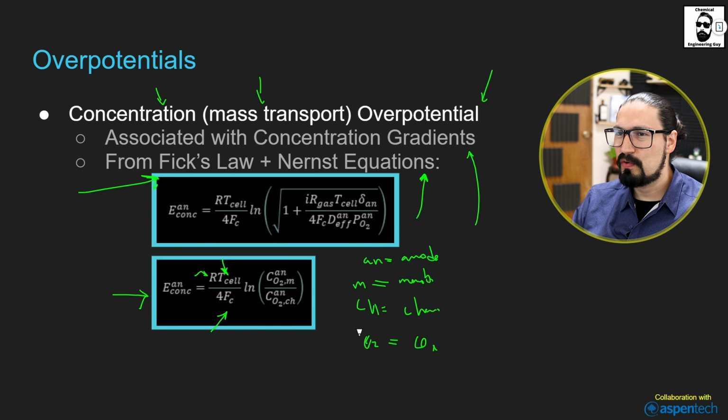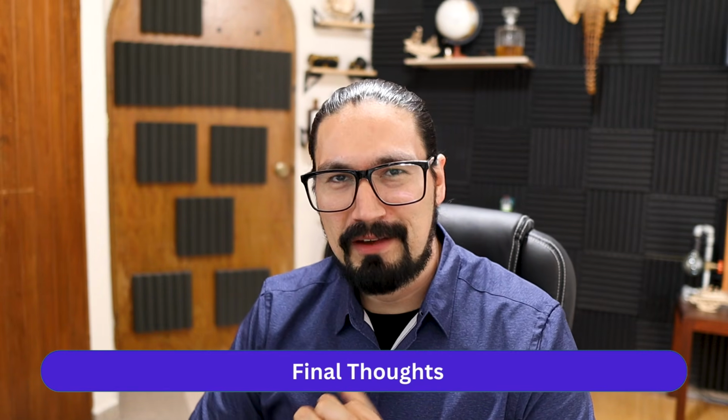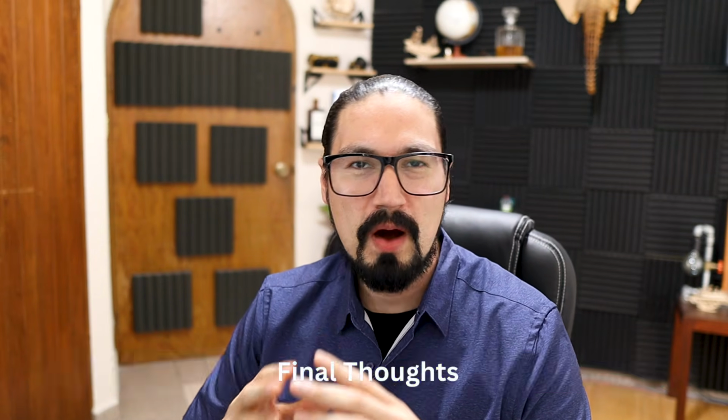This will be oxygen, of course, but later on we're going to account for the hydrogen value, which is going to be in the cathode membrane, and the hydrogen value that is going to be in the cathode channel. So yes, this is how we are going to be evaluating the overpotential for the mass transfer, which we already know is the main limiting factor whenever trying to go in the forward direction. So there you have it. This was a lecture that definitely went very deep into how to model an electrolyzer, either manually with a spreadsheet or eventually with a process simulator.